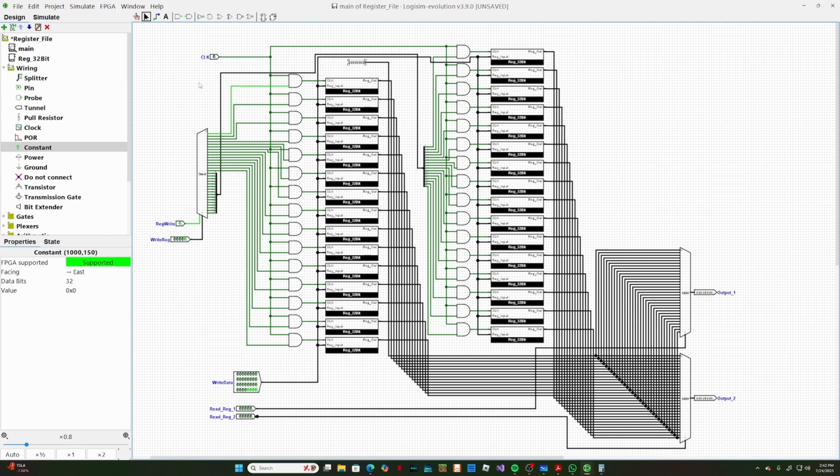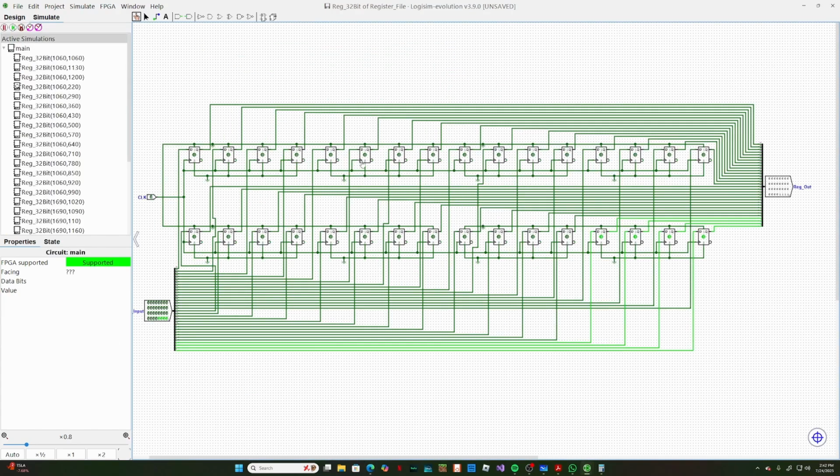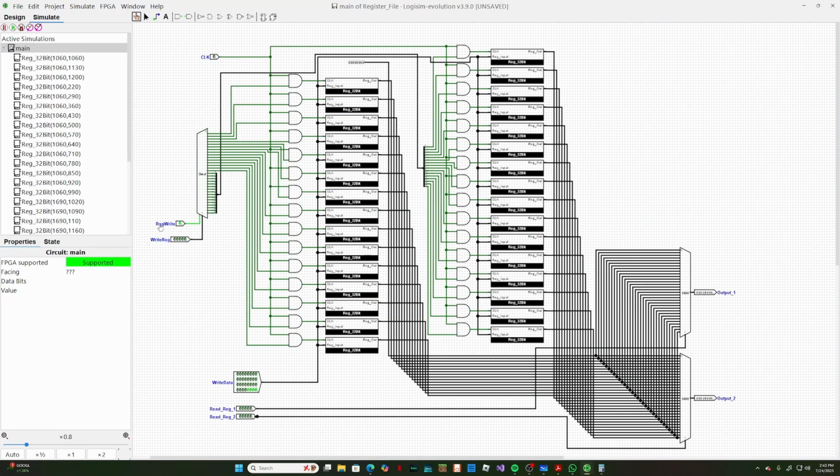And like you can see, there's no way for me to write into register number one because I want that register to always be zero. So if I put 00 and I try to clock it, you can see my output never changes because it's always zero. It's important to remember that my flip-flops are positive edge triggered, so it will only happen on the rising edge of the clock and only if register write is on. And if you go here, my register write is 1.